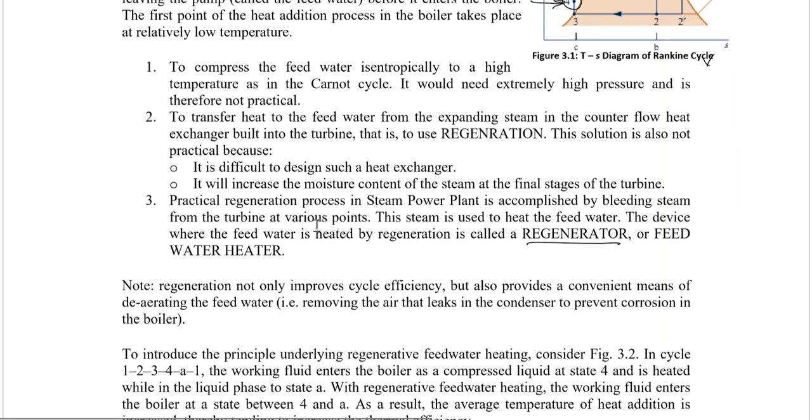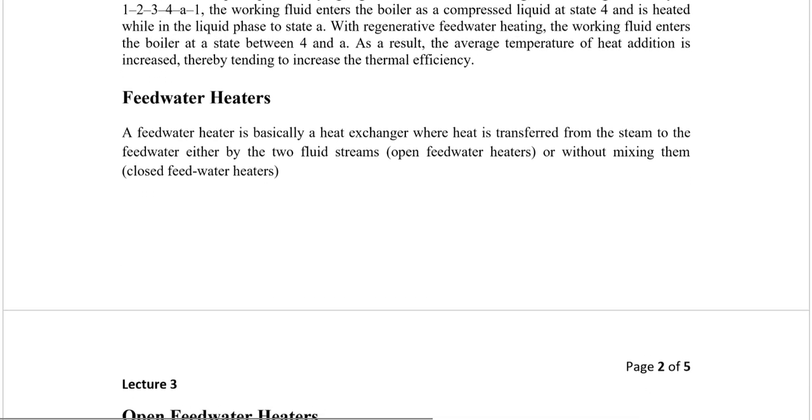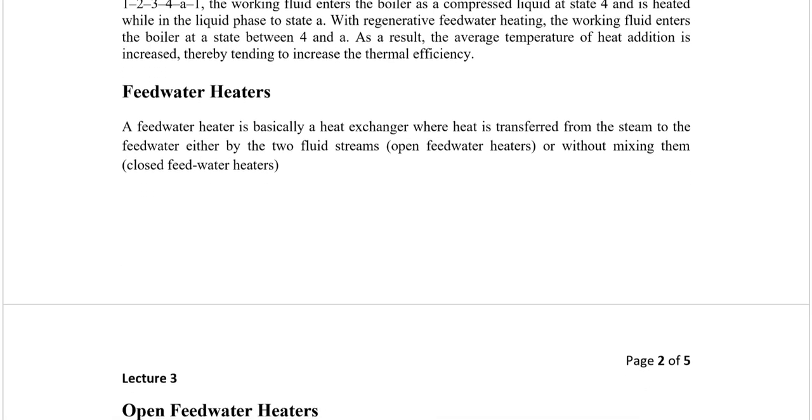So normally regeneration also improves the efficiency, and it also provides a convenient means of deaerating the water. That is the removal of air that leaks into the condenser, to prevent corrosion in the boiler. We will discuss it later on, but let's introduce the feed water heater first.